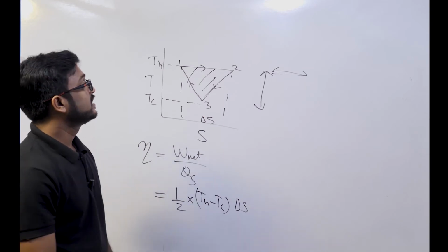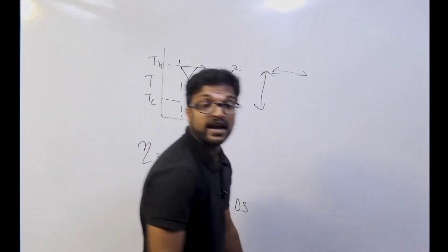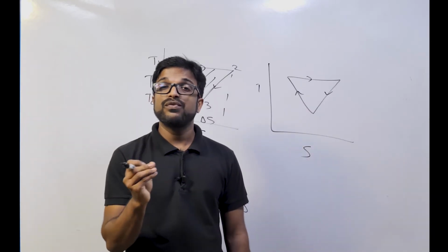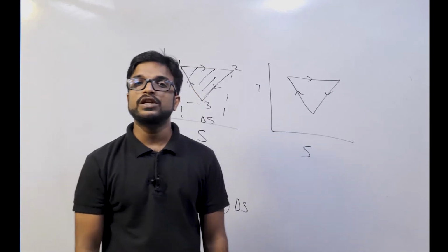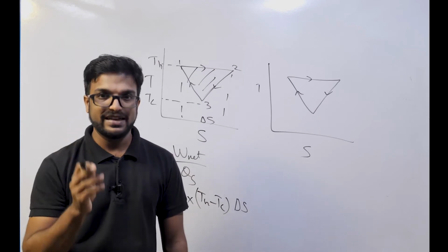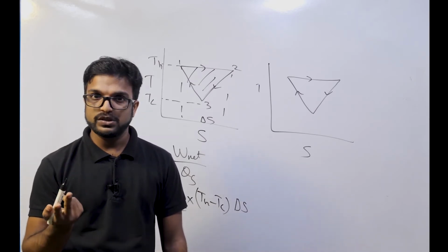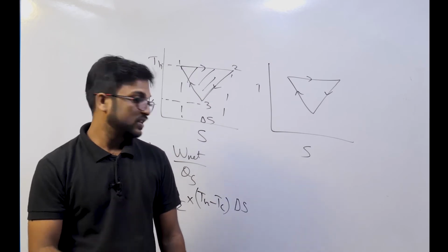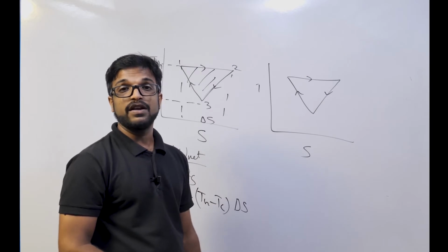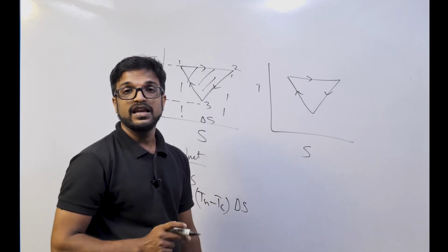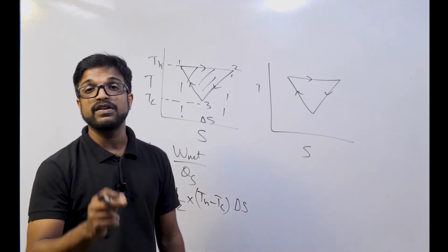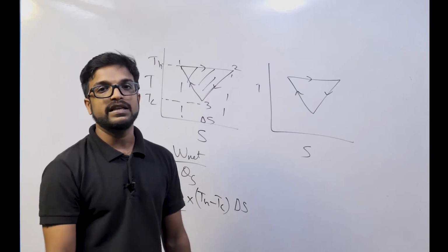Heat supplied, right? So here comes the twist. Can you find what is the heat supplied here? We have seen that if we are supplying heat to the system, its entropy will be increasing, right? dS is equal to dQ by T. If dQ is positive, the meaning is entropy change is increasing. In order to find in which process heat is supplied, we have to look at the direction of the process. If entropy is increasing in that process, then we can conclude that heat supply is happening.